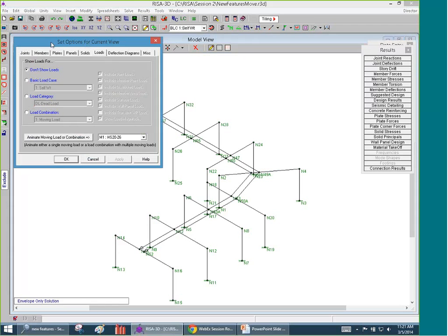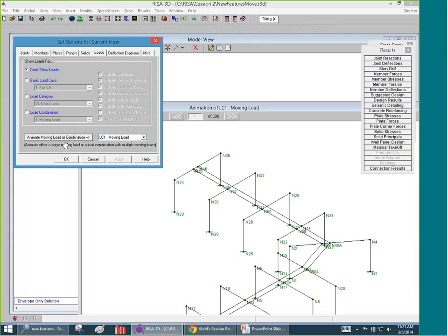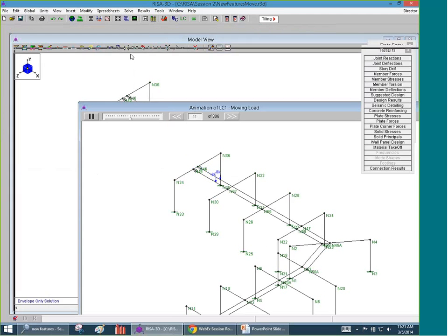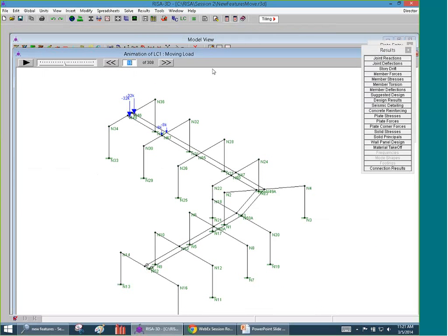Let's go back to my loads here and take a look at what is causing this and what locations might be causing it. So if I animate it and say OK, I'm going to pause it for a second. I'm going to type the numbers in that I was worried about. So 223 was one of the ones I was concerned with. If I click on that, I can see this is where the loads are falling directly on that member. So this is M3 here. This is the one that was getting caused at first. We can also type in different ones. Maybe 271 was one that was causing some problems. And we can see that might be where we land in the structure over here. So we've got maybe some failures in here.